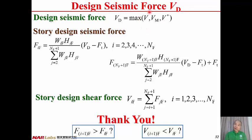The maximum of these three gives Vd, the design seismic force, and we use Vd for the design of the structures. After having the design seismic force of the structure, we distribute all the forces to all the stories. Then we can have Fi^F.